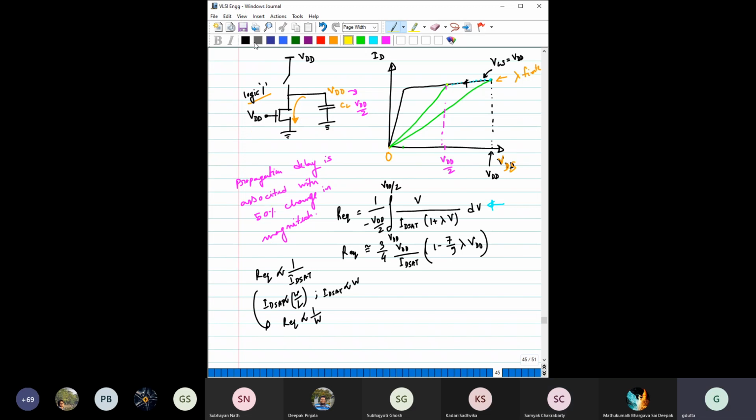Thank you. So you understand then the relation between this R equivalent and this W. Now what about this VDD? How do you think this VDD will impact? Since VDD here is in a square relationship and a downward facing parabola type curve, therefore up till the middle point where it attains the maxima, we can find an increase in resistance, and after that it will decrease.